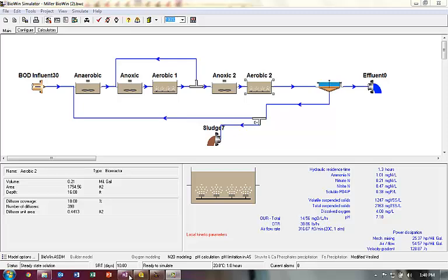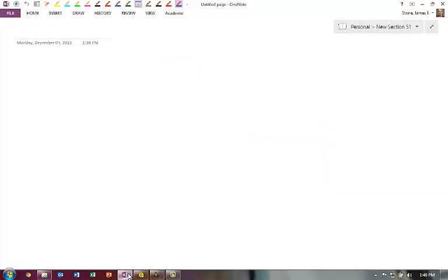So in your Challenge 2 and 3, as I mentioned in class, I would like you to track the energy that is being used in those basins for your particular designs. And so the parameters that you can track, and I'll show you where those are located at, options. So you've got the oxygen uptake rate, OUR, and all this is again in Chapter 5 in some of the oxygen transfer sections.